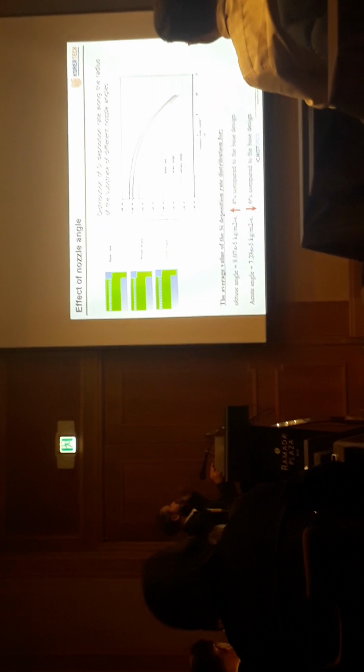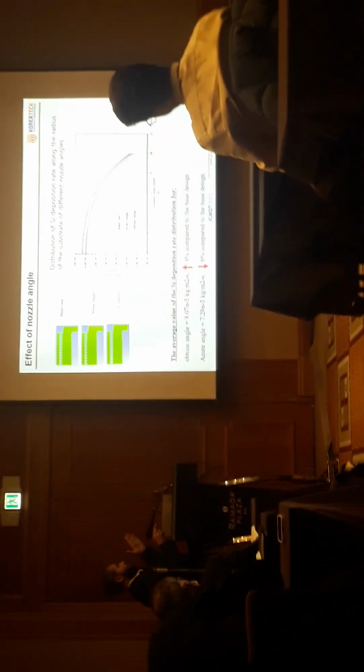And then we choose this nozzle to be also our target nozzle, and then we go further to do analysis for this particular nozzle and study the effect of the outlet angle of this nozzle. We use the base case, and then we choose a small obtuse angle and acute angle, and you can see here that the obtuse angle is giving better performance, while the acute angle is decreasing performance by 6%, and the obtuse angle is enhancing it by 4%.